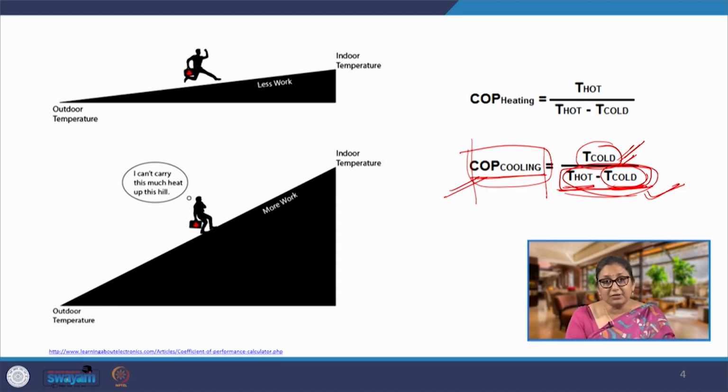I will stop here today, and we will look at some examples of calculations for other aspects of building design and construction also, but largely related to scope 2 emissions. We are not looking at scope 3 emissions and the calculations where embodied energy and life cycle emissions are concerned. We are largely looking at scope 1, which is direct emissions, and scope 2, which is emissions through purchased electricity, purchased energy.